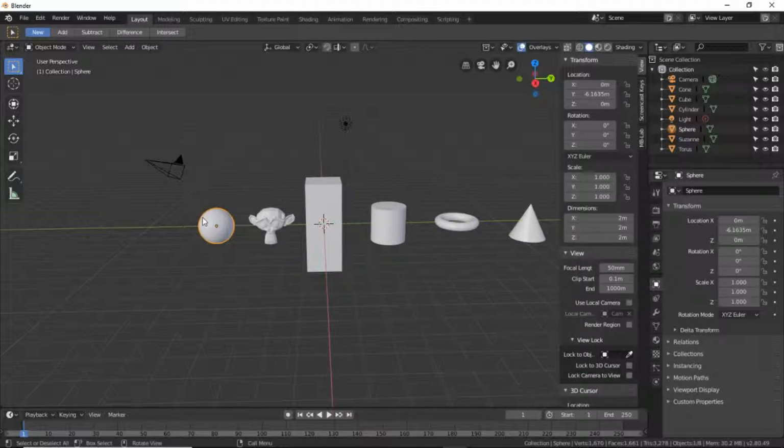If I want to select more than one object, then I hold the Shift key and use the left mouse click to select. In this case, I am selecting the UV sphere and a cube to the sequence. Notice that the outline of the object I selected last is yellow, and the previous object's outline became orange, indicating that the cube with the yellow outline is the active object of the selection sequence. Some Blender tools rely on the active object of the selection sequence, like parenting or Boolean tools.